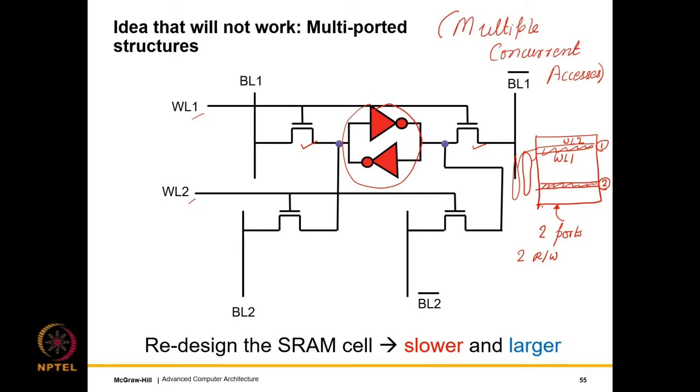We can instead design the SRAM in such a way that we have 1 read-write port and just 1 read port. So the other read port will not have a write driver, will not have the facility for writing, but it will have the facility for reading. Similarly, we can say that look, instead of a generic read-write port, we can have just a read port or just a write port. So this will reduce the amount of hardware, but its architectural implication needs to be understood.